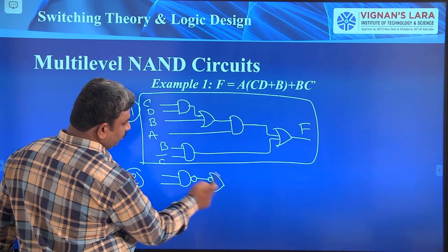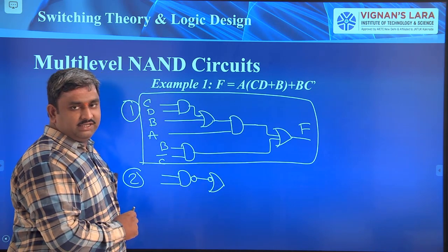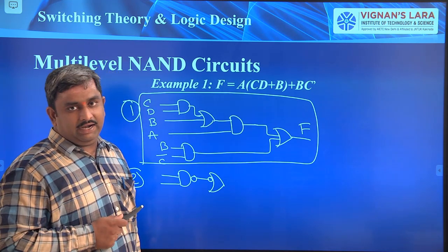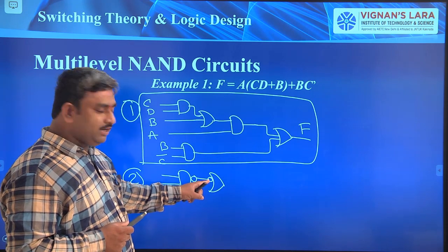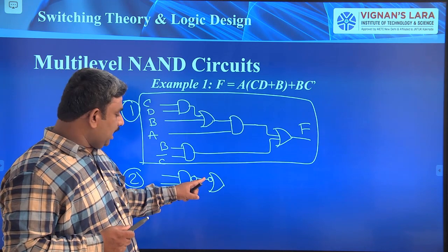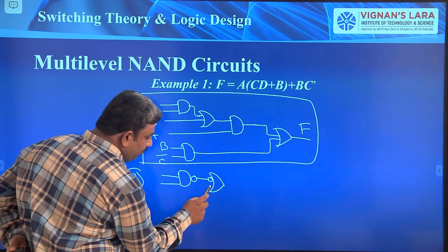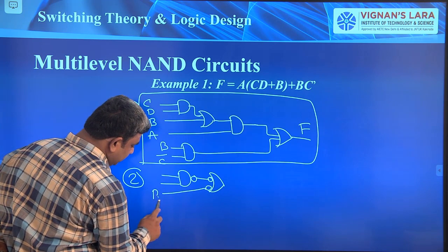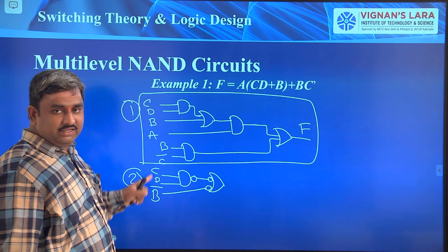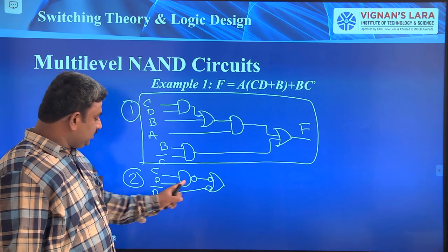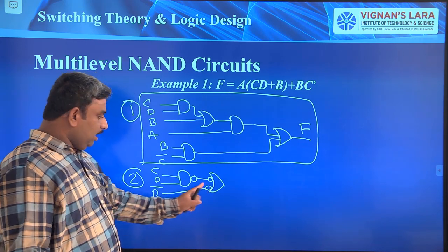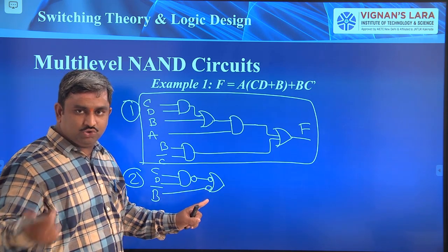So this is the OR gate I have drawn here, and here B signal is there. I said previously, a bubbled OR we can replace using NAND gates. For that reason, one input is bubbled, neutralizing the NAND gate with the AND gate. I have placed one bubble, and B signal is there. For B signal also I have placed a bubble. Now here the input is B bar. Here the CD signal is as it is. So B signal I have changed to B bar. Then this bubble makes B bar to B. B bar and inverter, B double bar, then it becomes B.